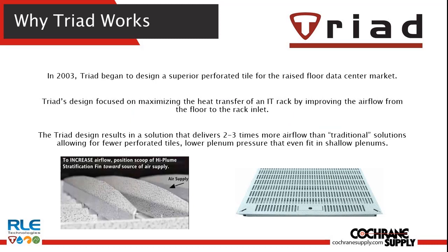So how did Triad really get started? Mainly due to the need for improved airflow inside of the raised floor data center market. The focus was really to maximize the heat transfer of an IT rack by improving the airflow from the floor to the rack inlet. The design that's been patented delivers 2 to 3 times more airflow than a traditional solution, allowing fewer perforated panels, lower plenum pressure, as well as fits into shallow plenums as well.